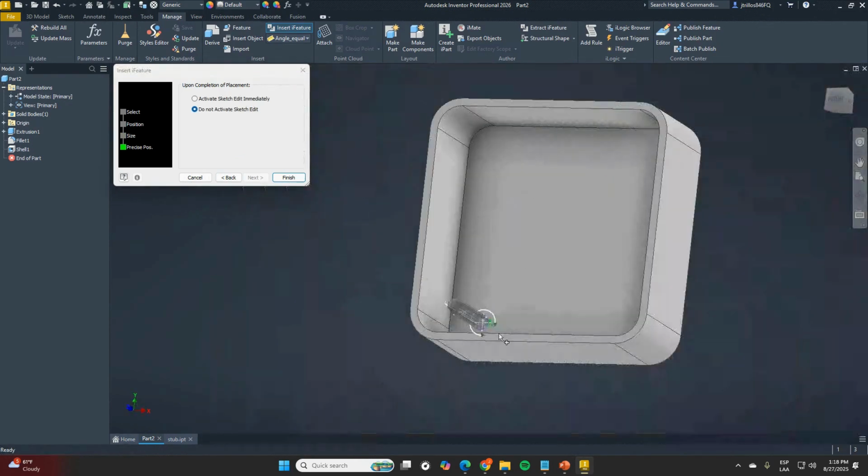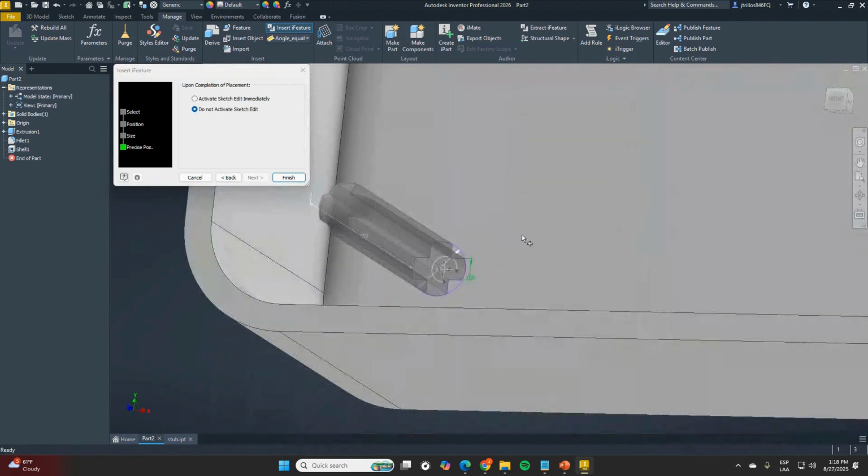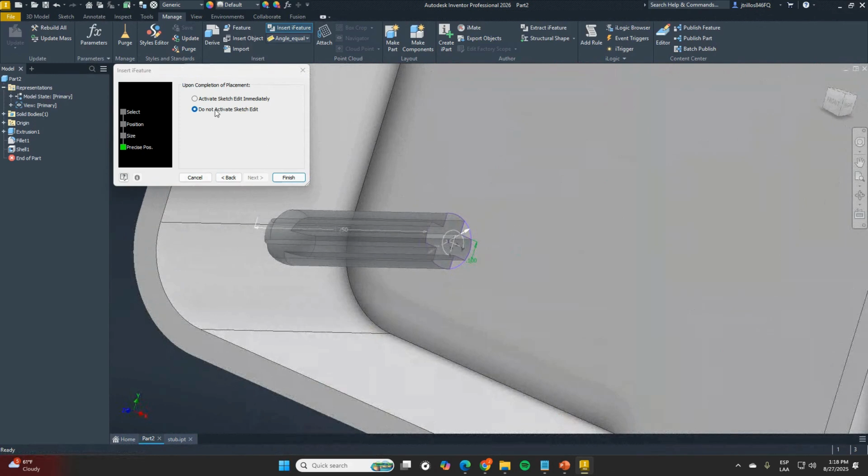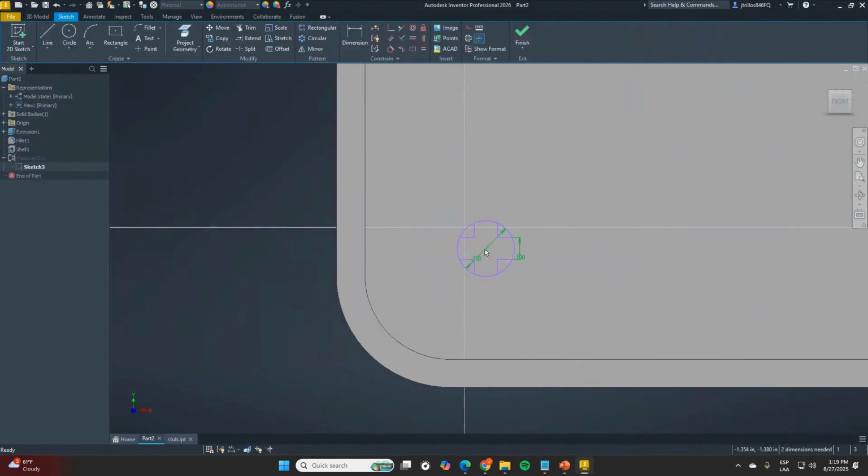And by the end, because the iFeature is based on a particular sketch, I can activate the sketch to place the iFeature exactly where I need it. Okay. If I do not activate it, it's gonna render the result that we saw before. That's it, right? We can modify it afterwards, but it's usually a good idea to activate the sketch as soon as you place it, so you can actually modify the sketch and place it exactly where you need it to be.